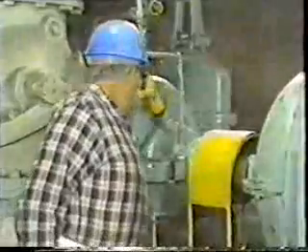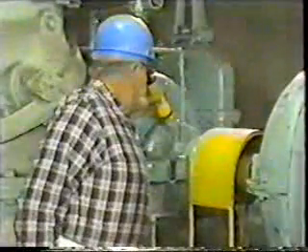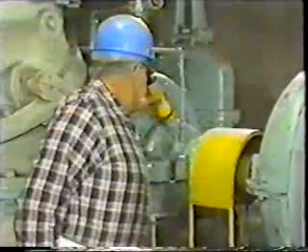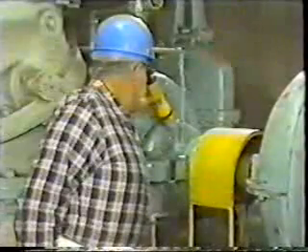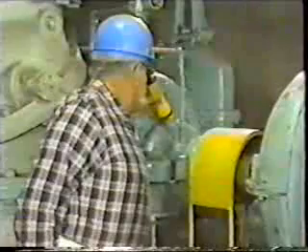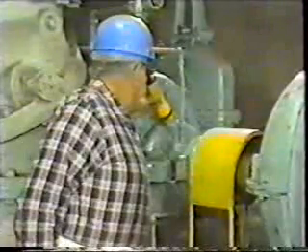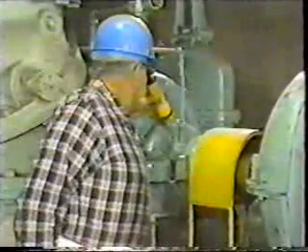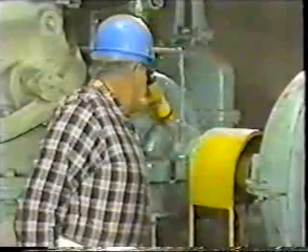So then he walks around to the other end of the pump to verify that the inboard packing is not leaking excessively. If the packing was leaking excessively on both ends of the pump, then it might indicate that there's been a change in the condition of the sealing water that has damaged the packing. On this pump, both ends would be equally affected by a change in sealing water, since both packing glands receive sealing water from the same source.